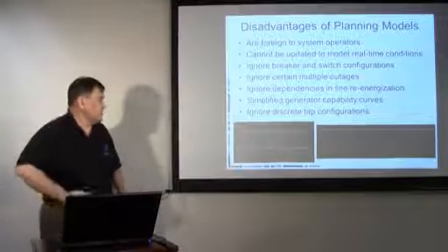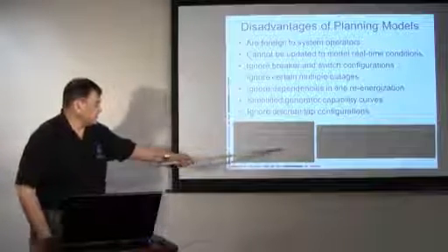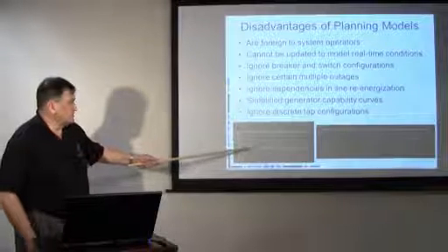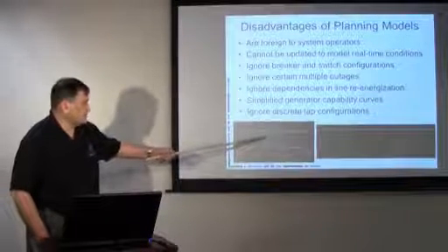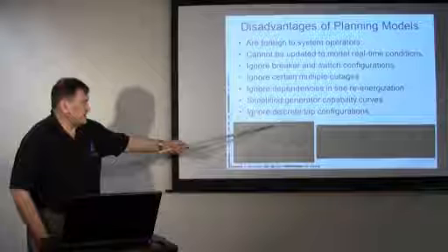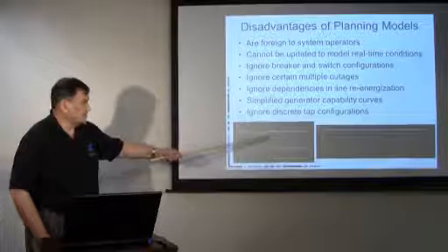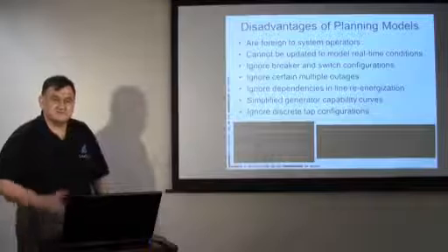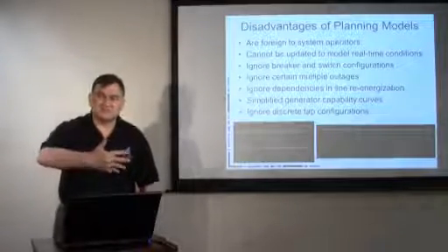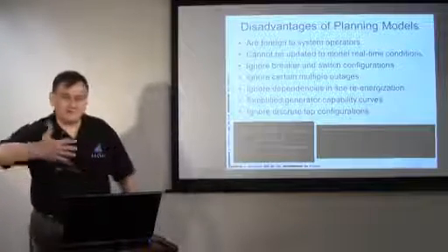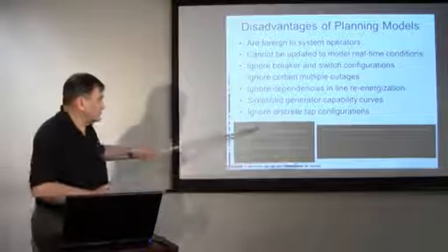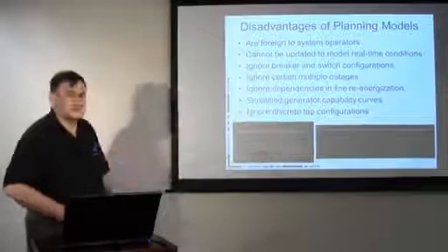We talked in a previous course about if we have a bus outage, let's say this bus is out of service, and I lose this transmission line here, that line is faulted, those two breakers will open, and therefore that line will also go out of service. A single line contingency will always automatically propagate to a double outage when you have a breaker and a half configuration and one of the buses is out of service.